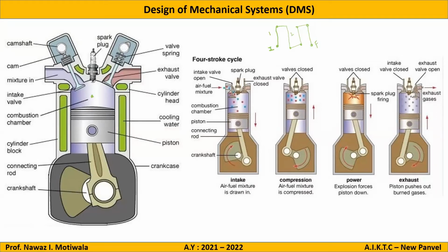Okay, so the same thing I will also repeat in some more technical terms. The things which you explained were exactly the correct ones. So let us say the first cycle starts with this air fuel mixture. In this case, there are very logical questions and they can be a part of your technical questions like MCQs. In this first stage, what can you tell about the position of the inlet and outlet valves? Inlet will be open and outlet will be closed. Yes, in the first stroke, not first cycle, sorry, first stroke, the inlet valve will be open and the exhaust valve will be closed.